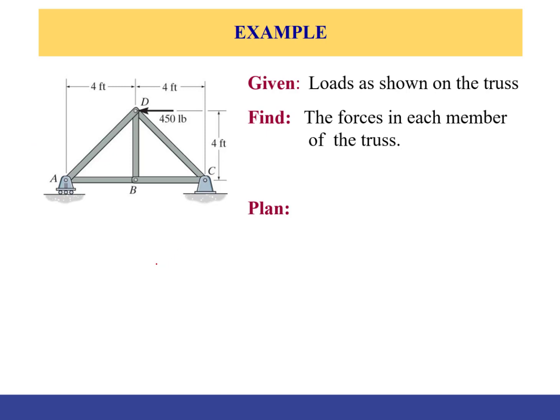For this not to rotate and not to translate, it must satisfy the equilibrium equations, which it does. The second thing is how many unknowns we have, how many supports. We have three reaction forces, which are sufficient to hold this system stable. So this is structurally determinate, meaning that I can calculate the reaction forces here and there, but is it required in this problem? It's not.